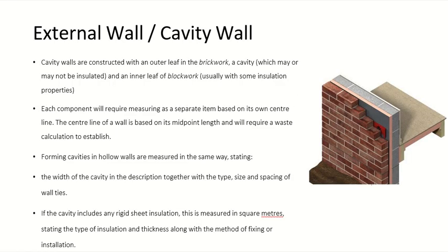External walls are normally hollow, they have cavity or something like this to provide the insulation. And if they have cavity, then you have to calculate each face separately and then the middle material separately, and we have done this for the substructure. The contractor may charge you for forming the cavity as well, because between the two faces you may not have empty space.